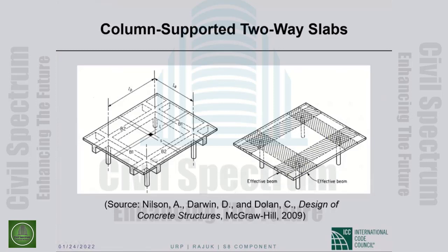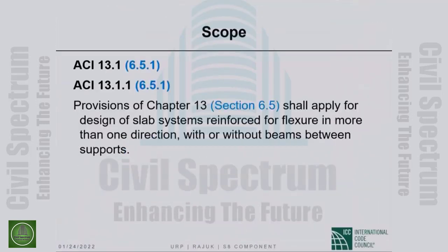So a flat plate has to transfer 100% of the slab load by bending in each orthogonal direction. This is something fundamental that was not understood at the beginning of the flat plate back in the 20s and 30s. By the 40s, I think most engineers understood this, but before that, there were problems because of a lack of understanding of this fundamental, that a flat plate transfers 100% of the slab load by bending in each orthogonal direction.